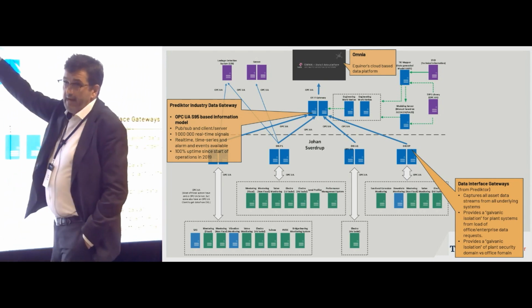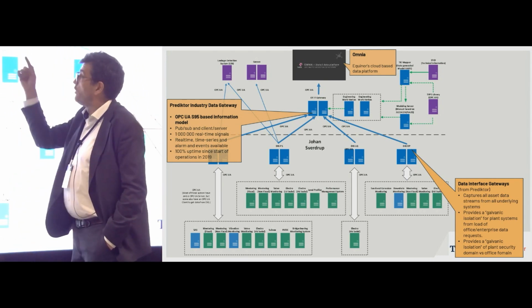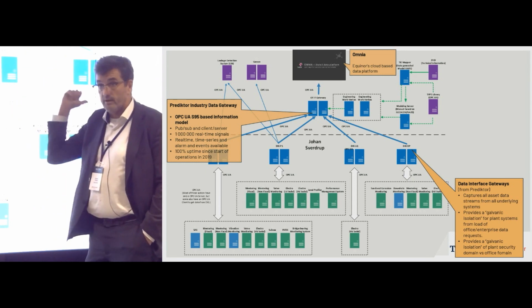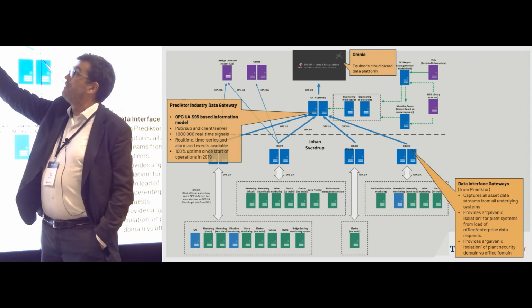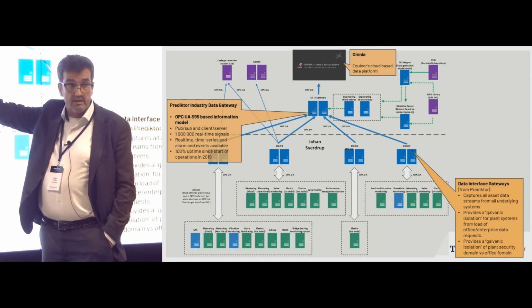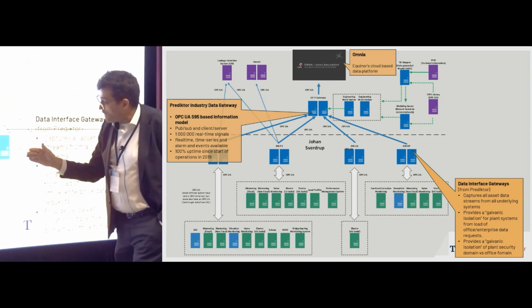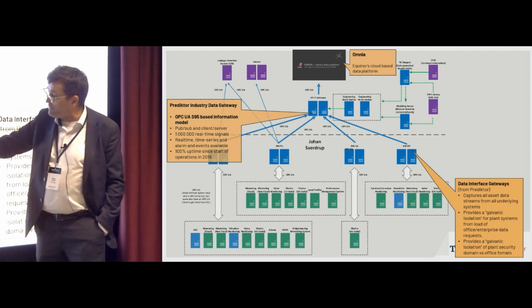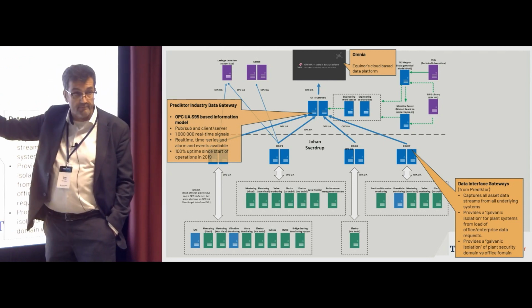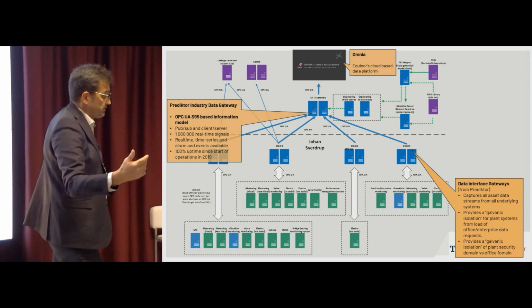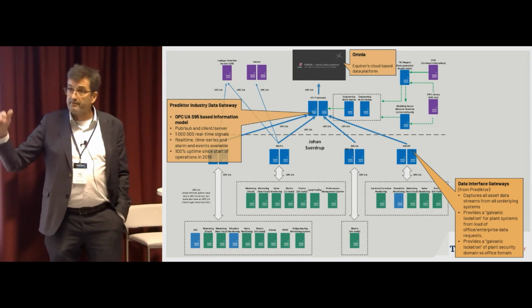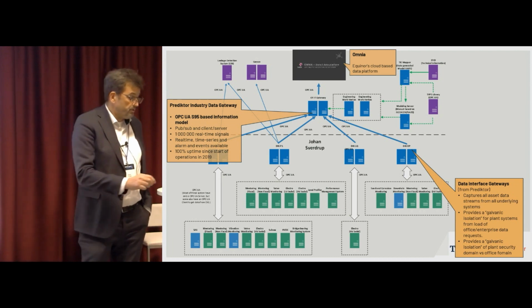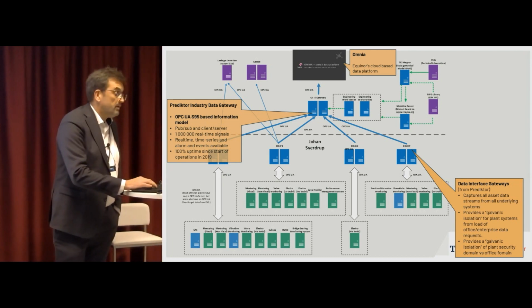So anyone with access up here will never come down here. The only one that has access down here is the gateway, right? And all the load to the system stops from the client up here, stops at the gateway. The only load down here is the subscription this gateway has up here. So also separation of load. So this is important structural architecture to protect the plant systems to be running efficiently.